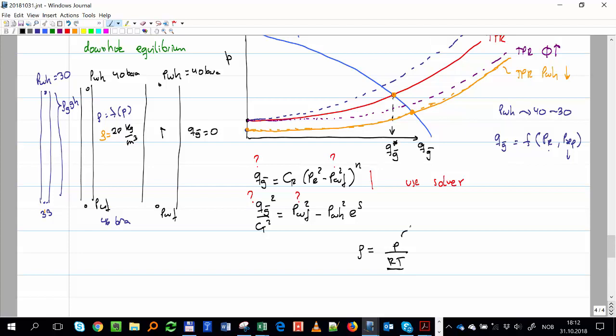If I have here 30 bar or 40 bar, that means if the pressure is reduced, the density is also reduced. If the density is reduced, that means the hydrostatic is also going to be lower than in this case. So here instead of having a 6 bar difference, now I will have maybe 3. Therefore this one was 46 and this one now is 33.